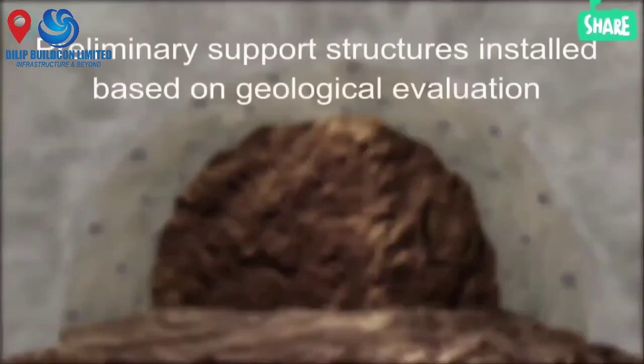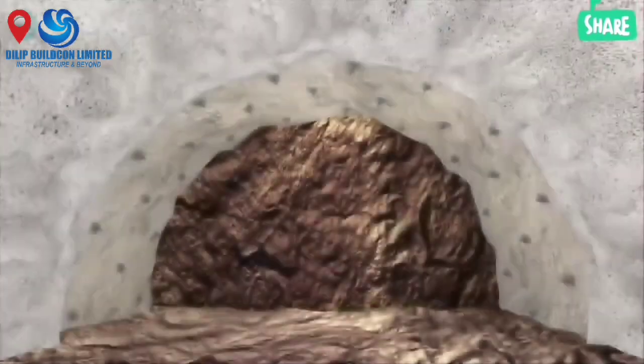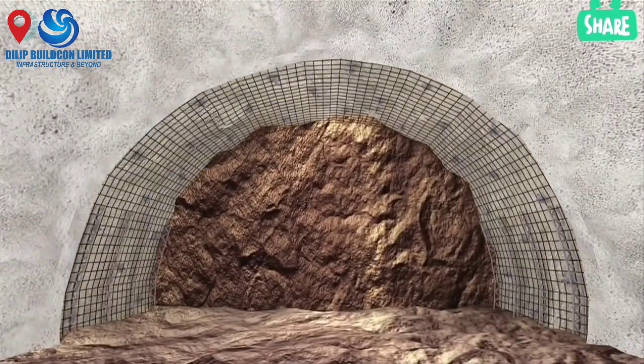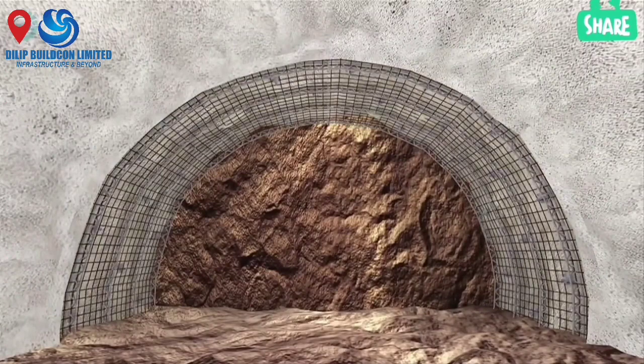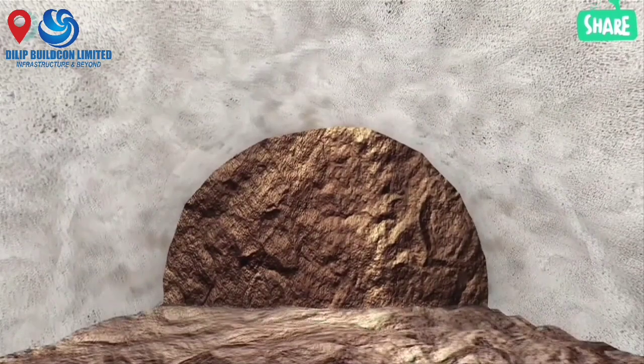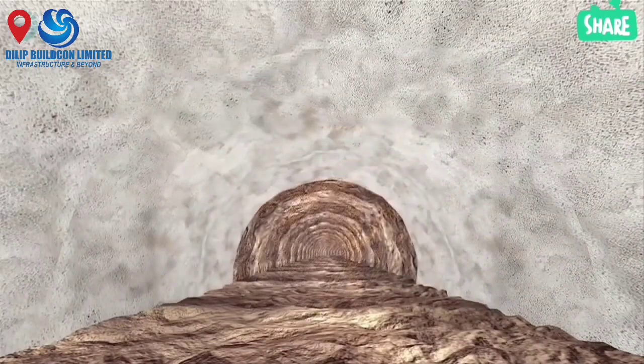As per requirement and based on the geological evaluation done by geologists earlier, preliminary support structures like wire mesh or lattice girder may be erected, after which a final layer of shotcreting is done. The process is then repeated for the next round of blasting as per the requirement.